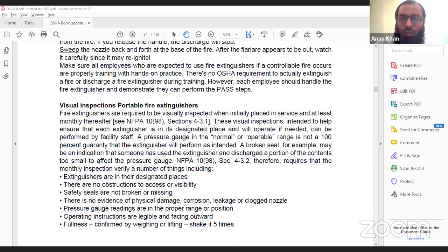The first thing I want to tell you is that in a DCP fire extinguisher, we have 2 mediums. One is the DCP powder itself, which is potassium sulfate, I think, and the other is the nitrogen gas. Nitrogen gas is lighter. Whenever you have a bottle, for example, this is your fire extinguisher, this water is heavier, it is down. And the remaining area, if you have gas available, it will be here. Similarly, when you have the DCP powder, this DCP powder will be going down with the passage of time, and the gas will be going up with the passage of time.